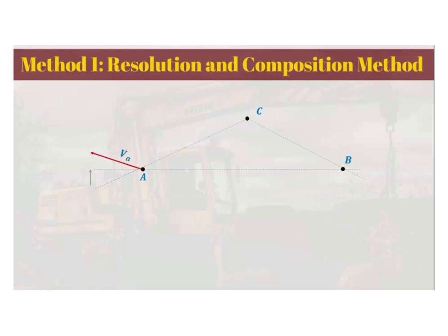You have the vertical component and a horizontal component along the line joining A with B. So as you can see now, the direction is towards left because of the direction of the velocity of A. So we are going to equate that the component along the line joining them is equal. So along this line AB, the component is, as you can see in the diagram.